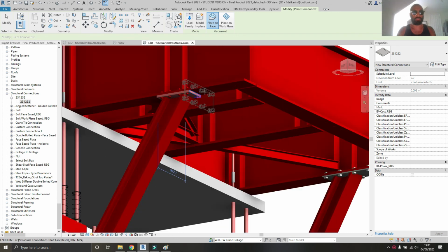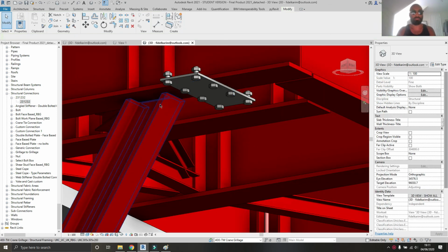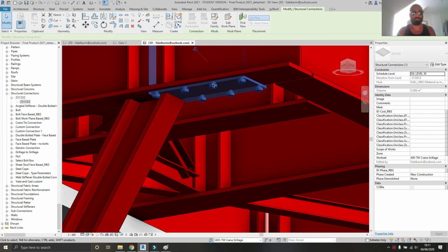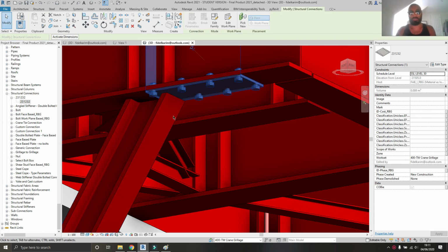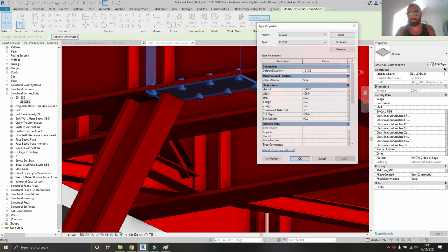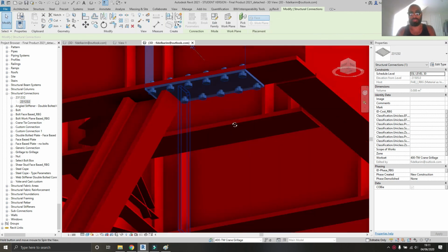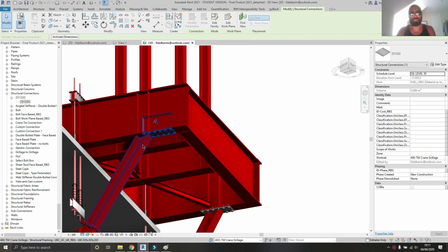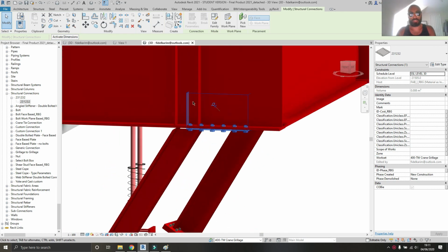Let's put one on this side. Delete that little group there. A space. AL for align. There to there. Assume it's in the right place. I just want to show you, let's say I want 6 bolts on this one and I want them to be smaller. There you go, boom, and then you can position it better, align it to wherever, and use it to cut things.